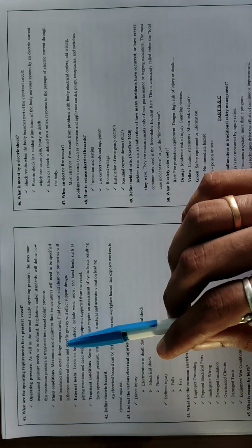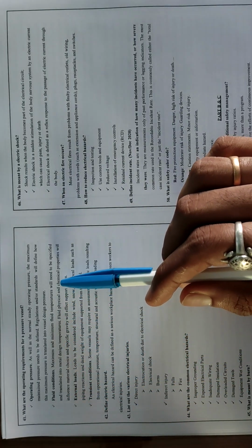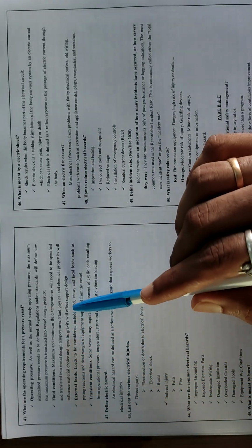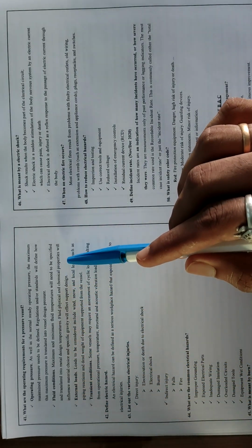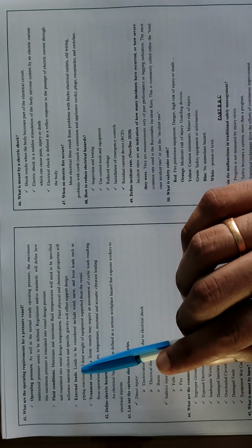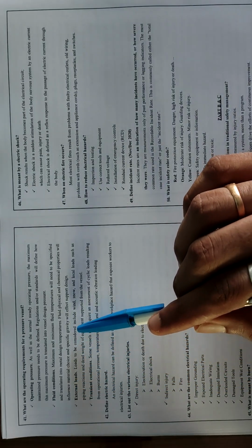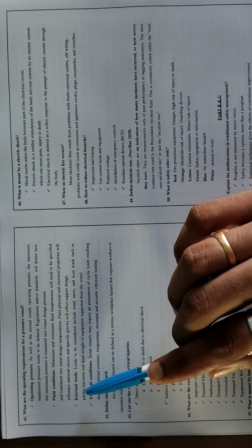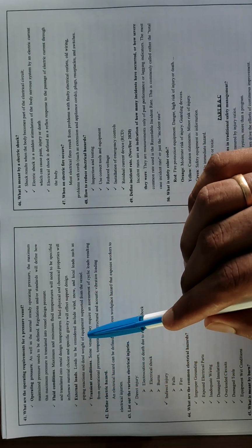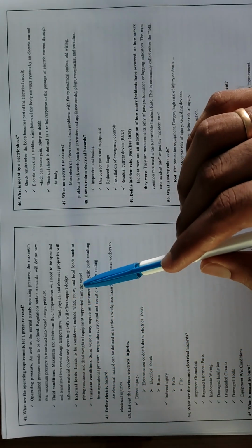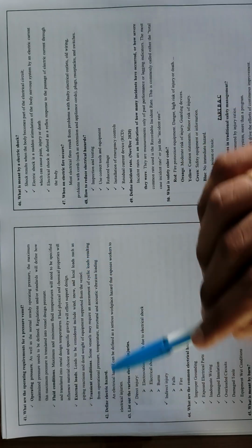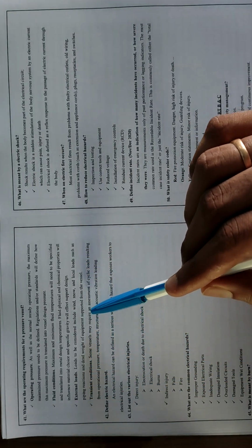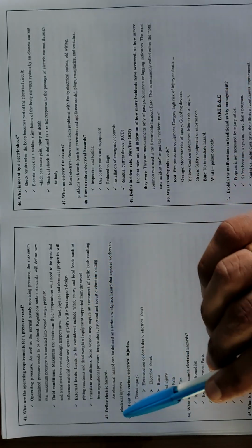Fluid conditions. Maximum and minimum fluid temperatures will need to be specified and translated into metal design temperatures. Fluid physical and chemical properties will influence material choice, and specific gravity will affect support design. External loads. Loads to be considered include wind, snow, and local loads such as piping, reactions, and dead weight of equipment supported from the vessel.